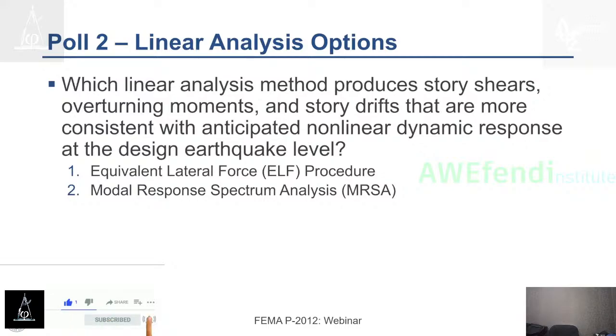Yes. And so it may fly in the face of your past expectations, but ELF produces results that are more consistent with the envelope demands from a nonlinear dynamic analysis. So, I mean, on one hand, I guess you could say that the framers of that method who developed it initially did a good job when they were trying to do some enveloping. And perhaps we fooled ourselves by doing more complicated analysis with modal response spectrum analysis, thinking that the answers were more accurate, and that's not necessarily the case.